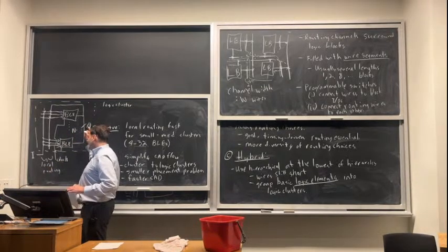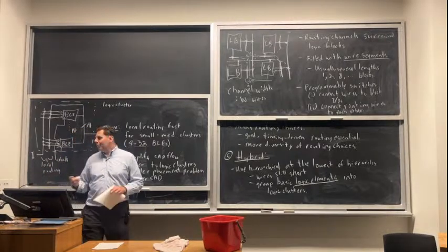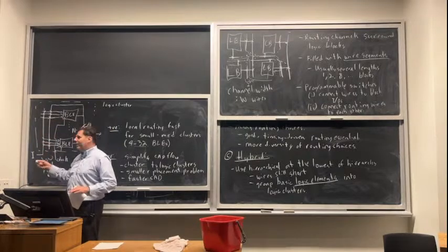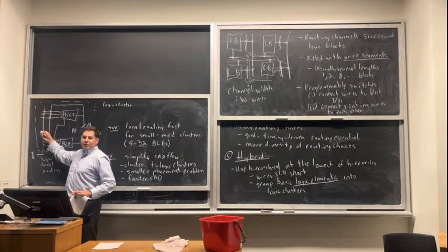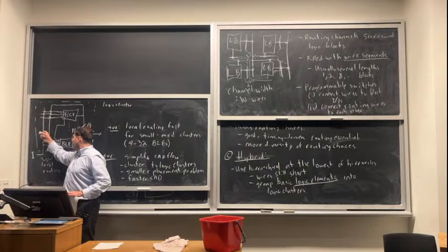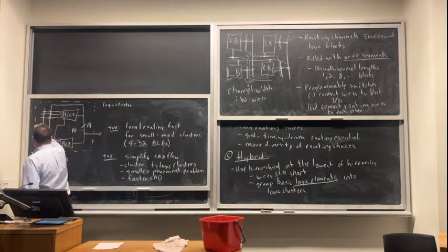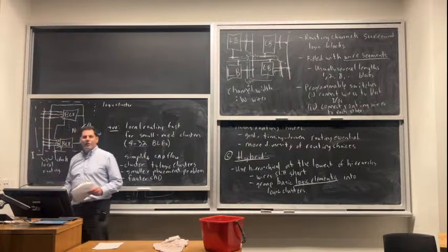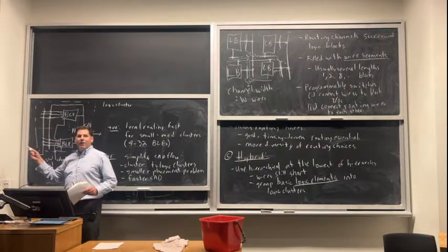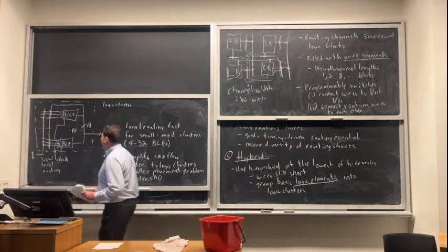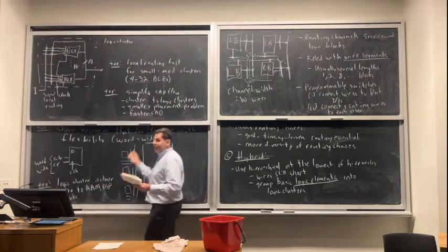So as we keep scaling, wiring resistance keeps going up. So these wires are not that long inside these logic clusters. But as we keep shrinking, even these wires can start to show significant resistance effects, meaning they might still be too long. So some architectures are starting to make essentially a more complicated hierarchical FPGA inside of here because the long wires, even these wires that aren't that long, can start becoming problematic. So that is a trend that's going on, as we move to really advanced process nodes.